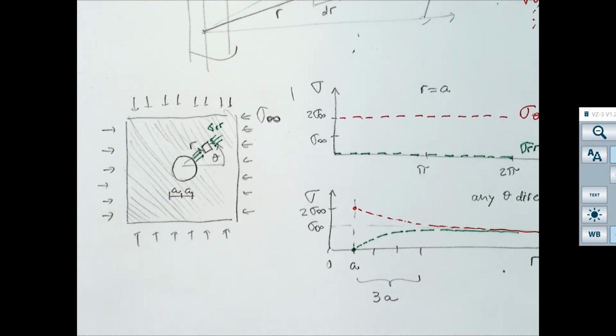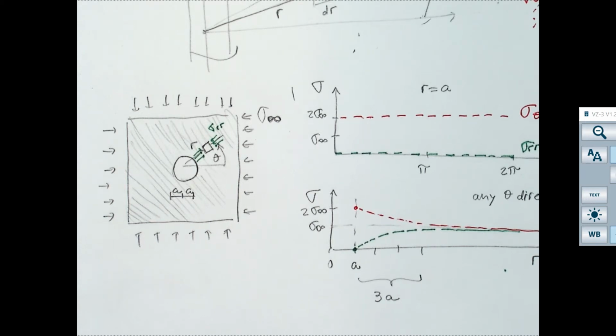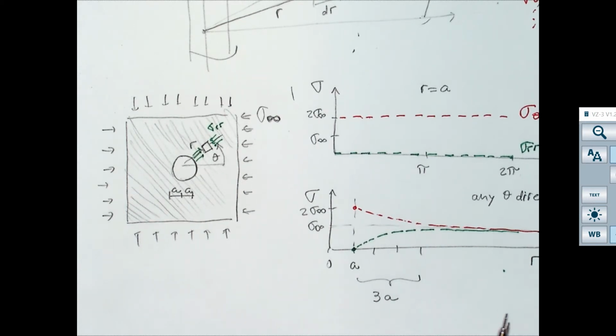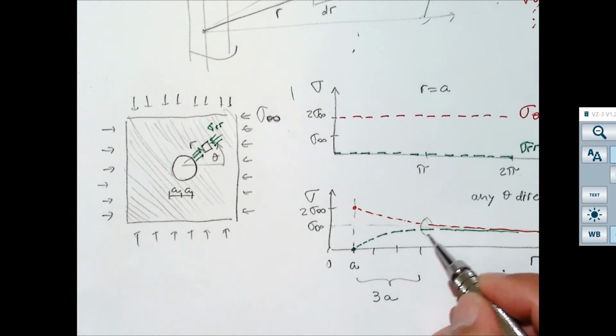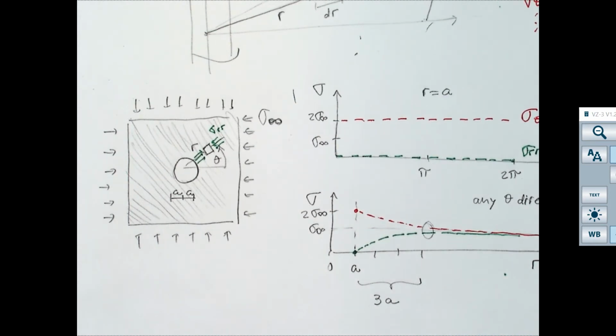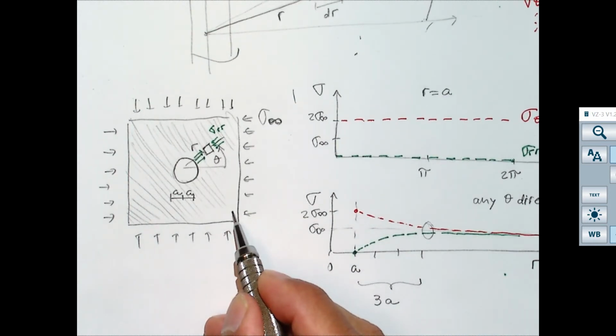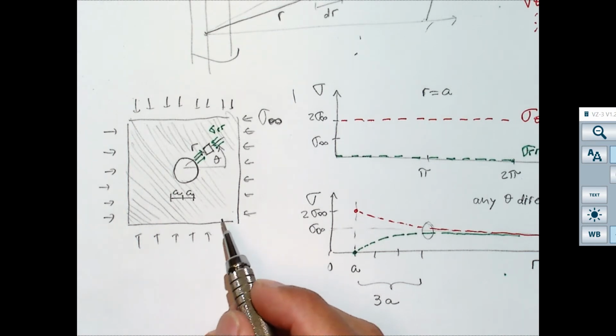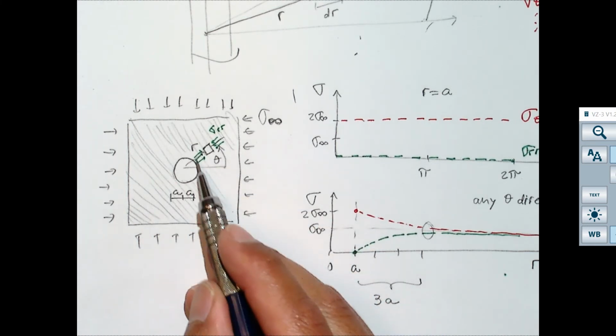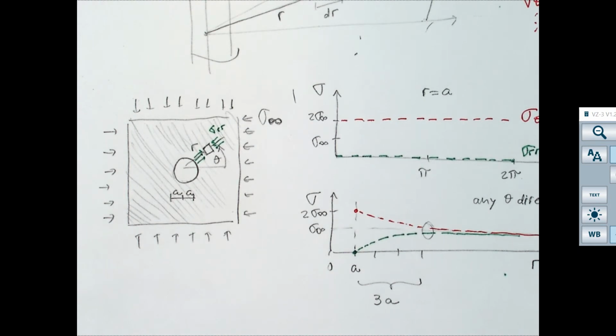You go 3 radii of the wellbore further away from the wall of the wellbore, and the stresses are already what are in the far field, somewhere over here. So the rock is just going to feel the stresses very close to the wellbore. You go a little bit further away, and all these effects of changes of stresses, that magnification of stress, just gets smaller and smaller.